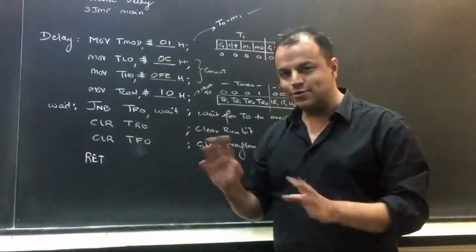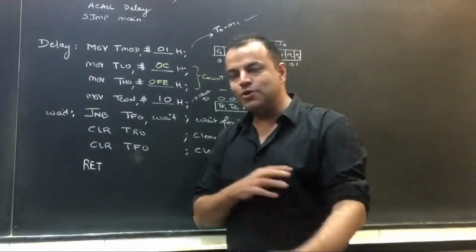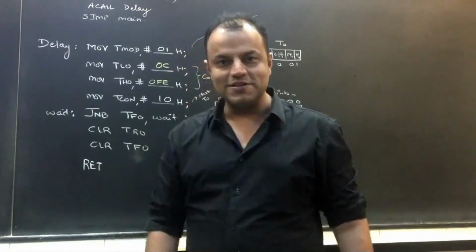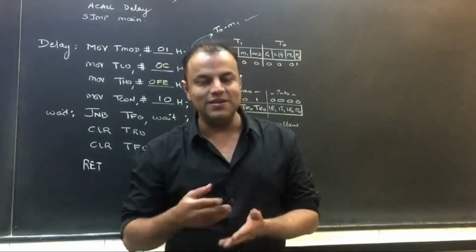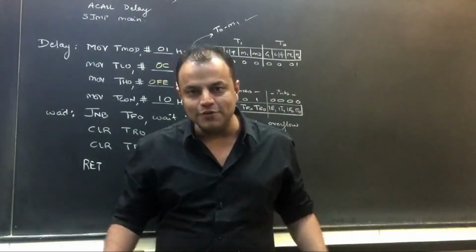By writing this line, you're not stopping the timer. Then what are you doing? What you're doing is getting the system back into its original state, because right now the system is in a funny state. The timer has stopped, but the run bit is 1. See the irony of the situation.